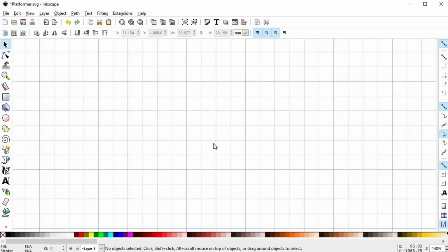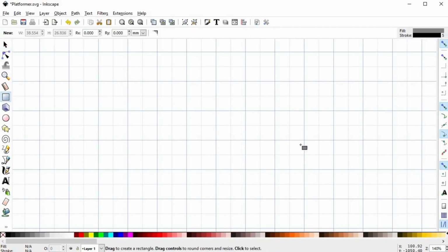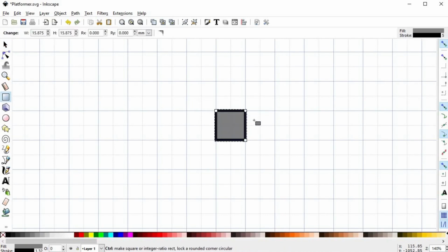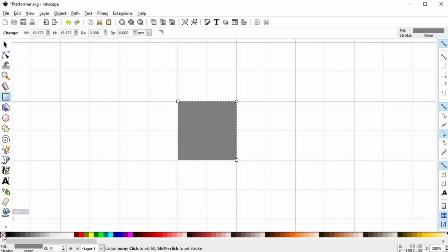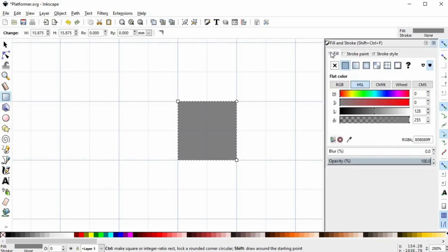Great, let's begin. Grab the rectangle tool, and with the option Snap into Grid enabled, draw a rectangle that fits a single major square. You should see the little blue X as you snap while drawing. First of all, we don't want a stroke in this object yet. You'll see why in a minute, so disable it. Now, in most Mario games and clones, question blocks tend to be of a light yellowish orange, so give it that color.